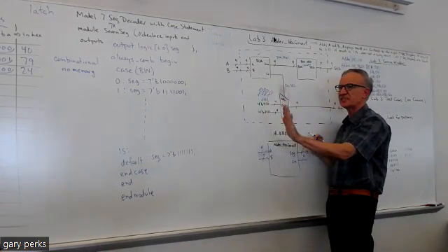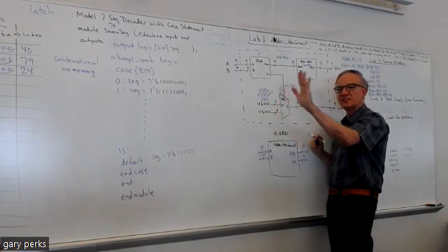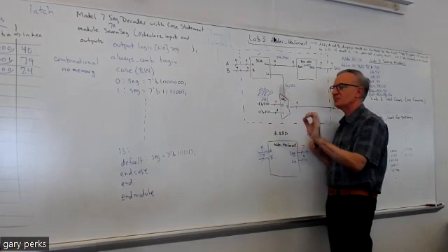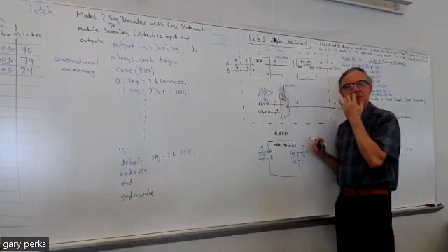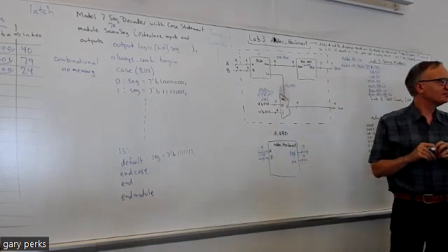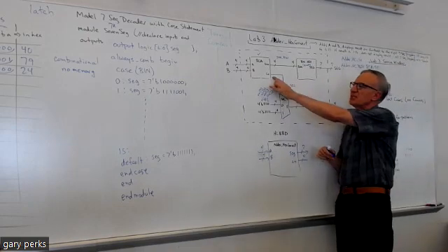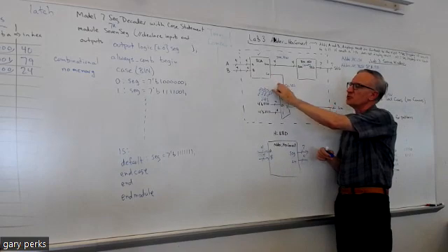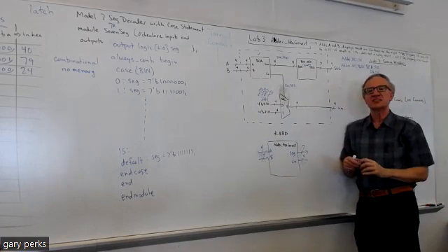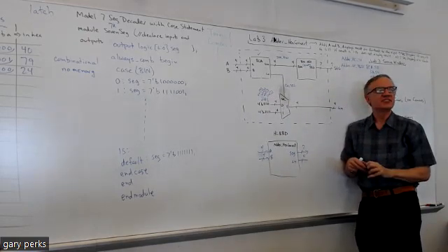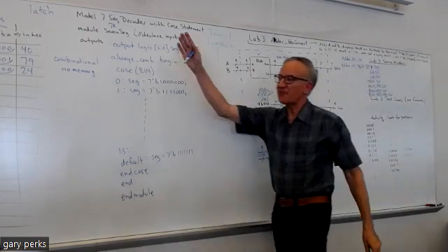This is the AN bit for the next display to the left. This is the AN bit that's 2 displays over from the furthest to the right, and then this is the AN bit for the display that's 3 over from the display that's furthest to the right. So can you see what's going to happen here? What's going to happen when my carry out is equal to a 1, meaning I have a result greater than 15? What's going to be at the output of this mux? It's going to be all 1s.